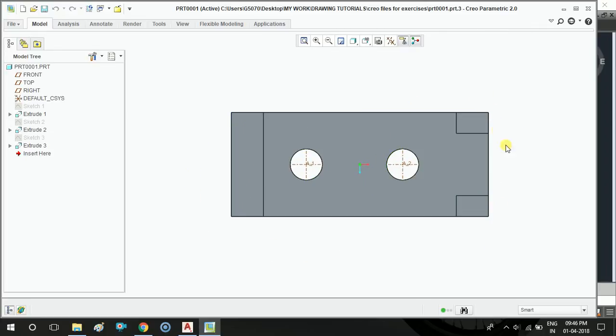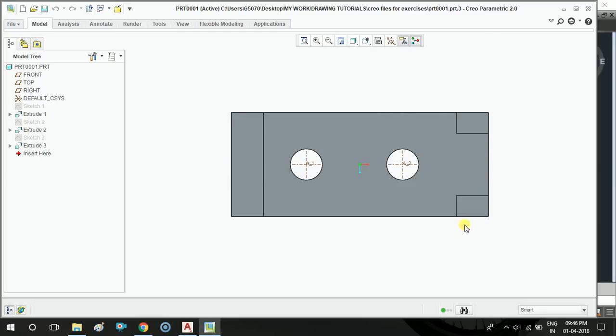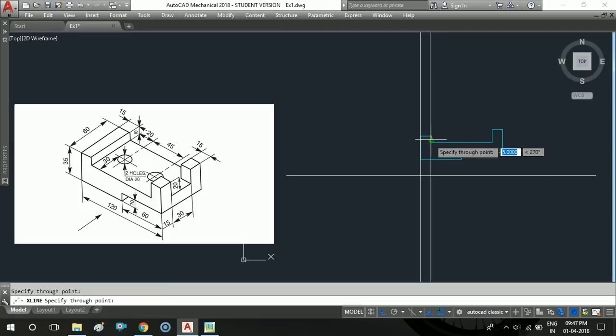So it is totally like a rectangle, with one parallel line of 15 mm, and these are two squares of size 15 by 15. And whatever line it is highlighting here will become hidden, because at the bottom some step is given. So finally we need to reduce the drawing, and for that we need to draw some construction lines, in between which we can get the required shape.